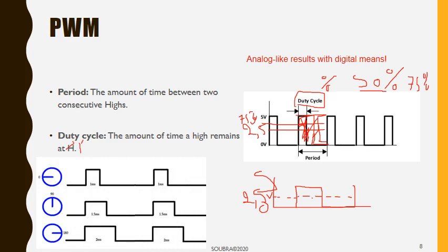I've explained the case of the DC motor as an example, and now let's use the example of the servo motor. We can conclude that this schematic belongs to a servo motor from the angles that we have here. If you define a duty cycle of, let's say, 20%, whatever the datasheet tells you is the needed duty cycle in order to have a particular angle, you're going to use it.